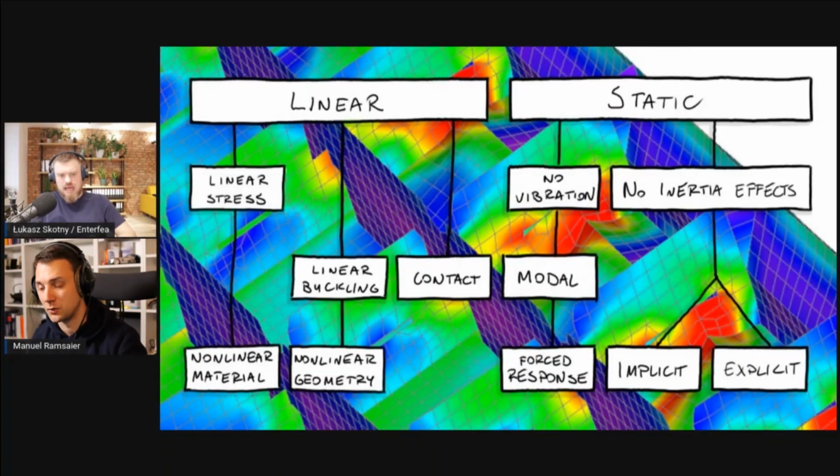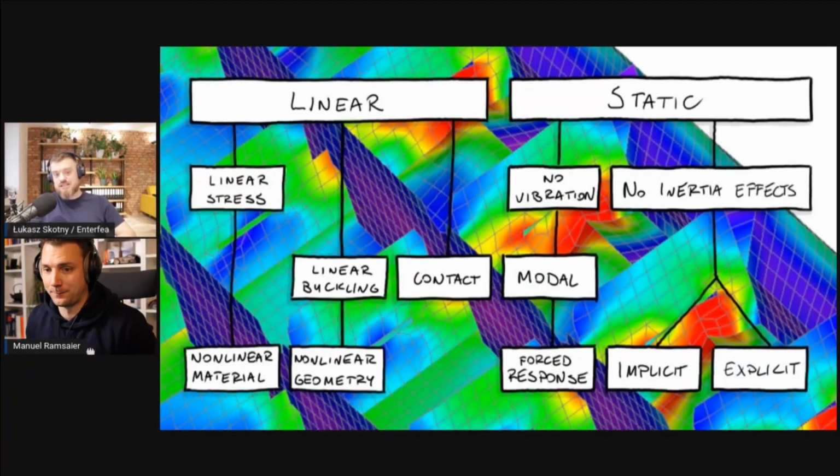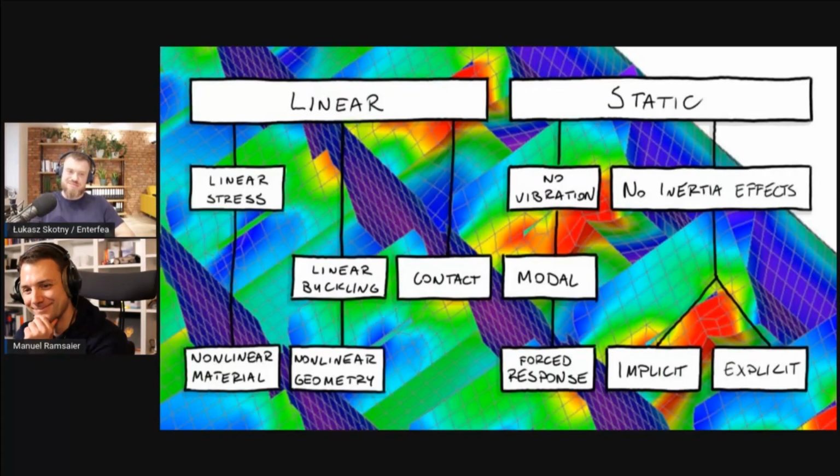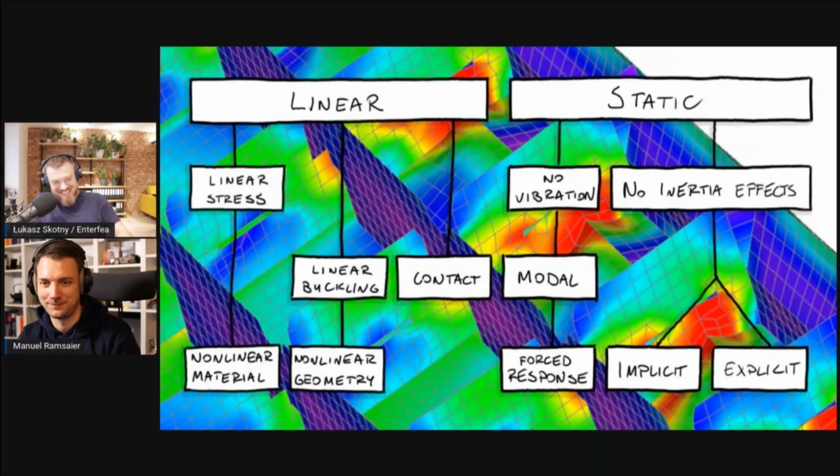Yeah, you have to make sure that it converges, not just your contact standard. Yes, because contacts are notoriously terrible to converge. It's right. I think that's the most irritating part of it. Even if we agree to call contact nonlinear, it would be the most irritating part of nonlinearities, because converging contact is sometimes hard.